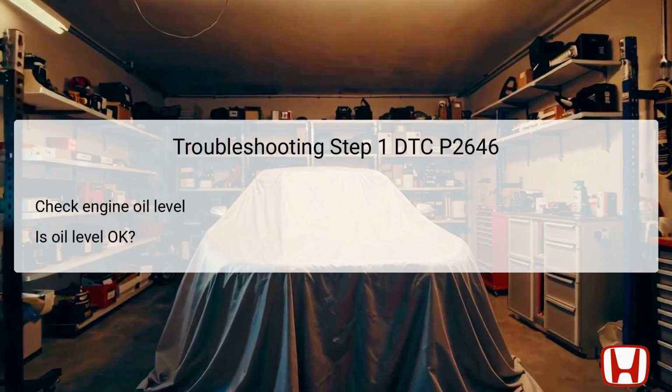The first troubleshooting step when confronting DTC P2646 is to check the engine oil level. This is vital, as incorrect oil levels can directly impact the VTEC system's functioning. You must ensure that the oil level is within the specified range to facilitate proper lubrication and pressure. If the oil level is too low, it can lead to inadequate oil pressure, triggering the low voltage code for the rocker arm oil pressure switch.